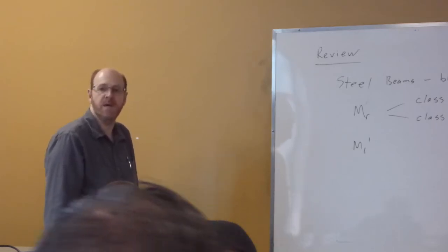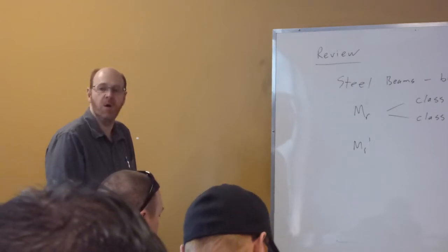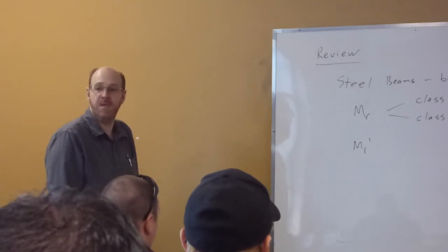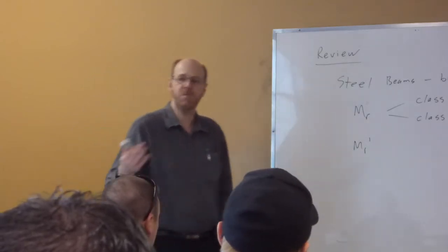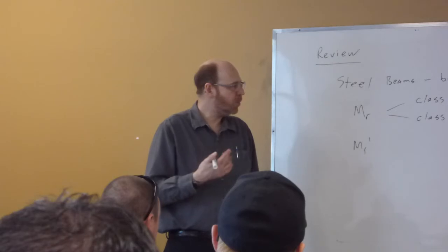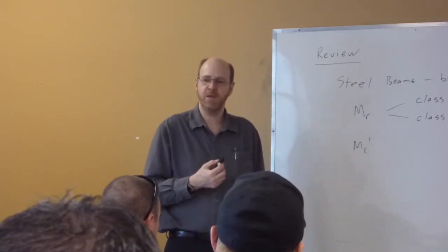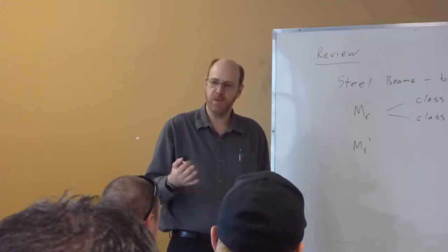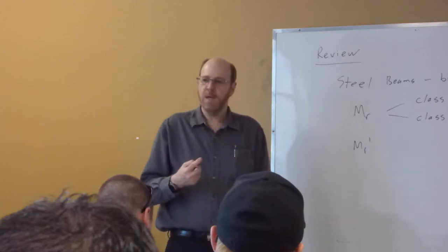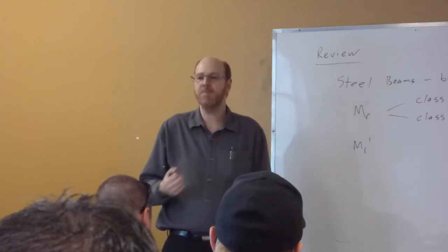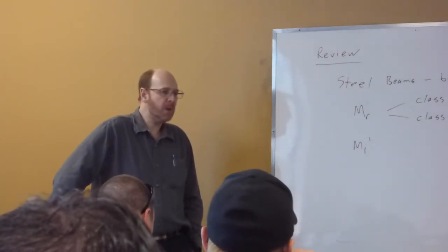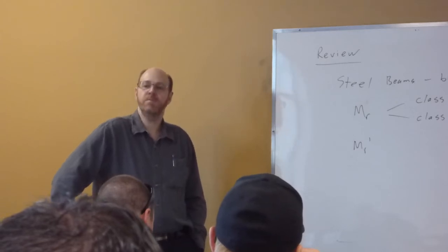There is actually, in the wood design tables, a separate set of tables for beam columns. Again, these are elements that have both bending and axial. They could actually be beams, or they could actually be columns, but usually they're columns with bending is the kind of scenario that we're looking at. It's much more rare in steel to have that kind of configuration, because typically our connections are such that we do consider them to be pinned top and bottom. So if we do happen to have bending, then we have some separate combined stress calculations that we need to go through. And again, they're just based on P over A plus or minus M over S in the two basic directions.